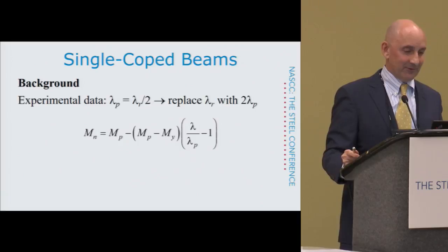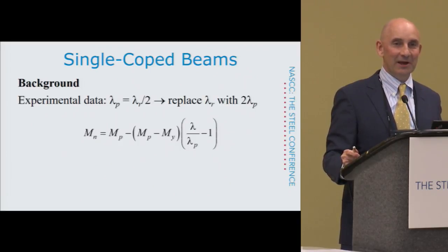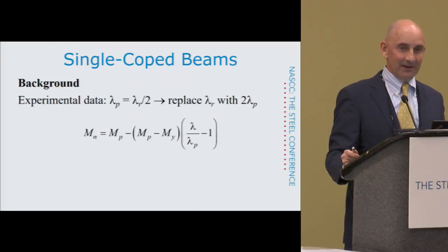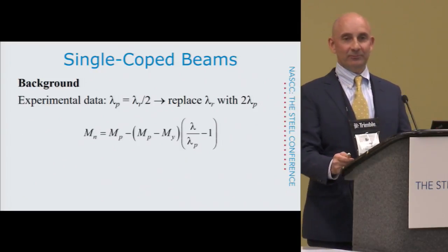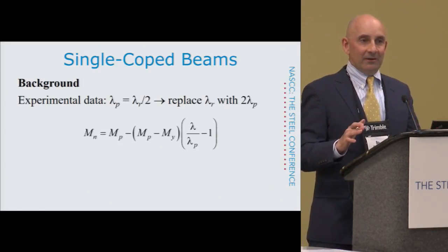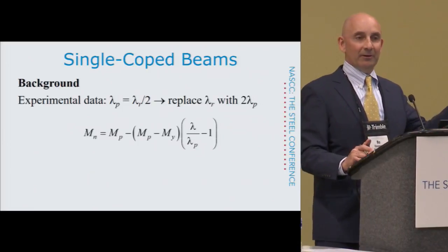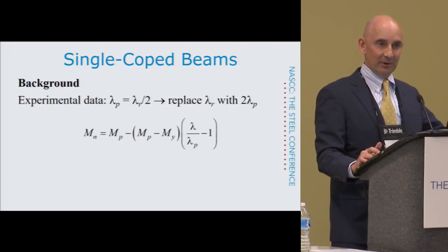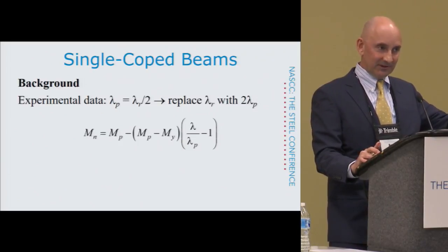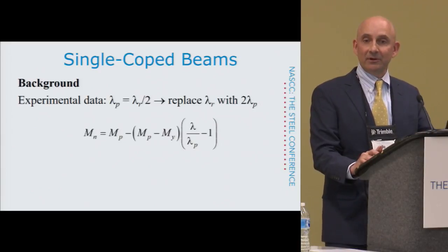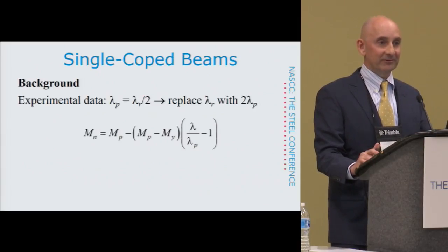Now, I have to give the credit for this idea to Tom Murray from a manuals committee meeting. We were looking at the data, and what we did, first of all, was take an approach very similar to what is done in chapter B, where you've got the tables for, say, a compression member, with lambda defined for local buckling, and then you've got lambda_R and lambda_P. Lambda_P is typically defined using experimental results.